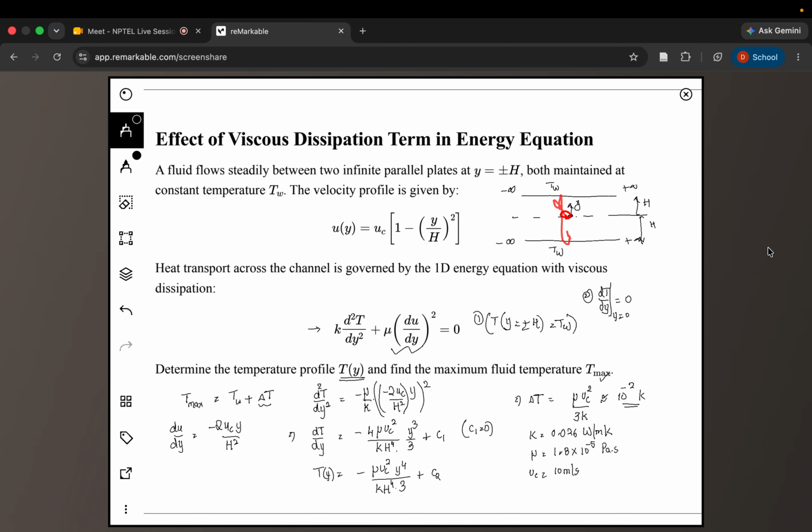So somewhere in the center, or for some other reason, if that happens, and whatever lubricant or engine oil you're using, if the temperature there exceeds the boiling point or the flash point for that particular one, then it will just evaporate there. Sometimes that can also cause deterioration of the materials. If you have, say, a ball bearing, and you design for a particular temperature, but the operating temperature is actually way higher than what you have designed for, that could also lead to failures.